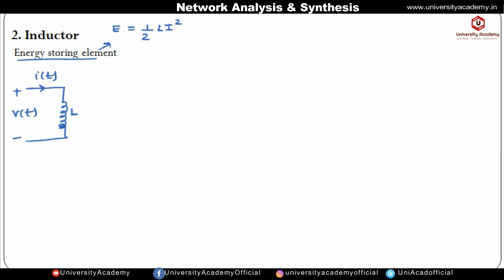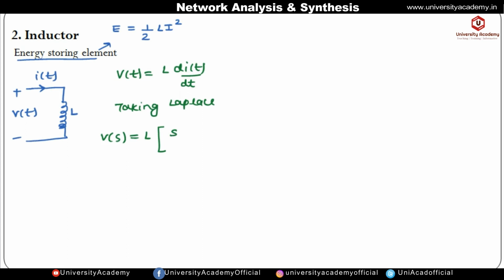So now we know that the voltage across the inductor, that is v of t, is given by L into di by dt. Now if we take the Laplace transform on both sides, v of t becomes V of s, then L, then using the differentiation in time property, what is the Laplace of di by dt? Here it is a first order derivative, so s to the power 1 into I of s,